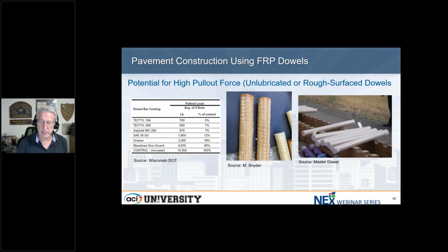Quite honestly, you ran your hand across it and you picked up little fibers into your hand, and your hand itched for a day afterwards. Not good. I wouldn't trust that. Even if you lubricated that, I don't know that you'd get proper slippage on that. So we need a good smooth surface. And if you don't have it, then you've got potential for a problem.